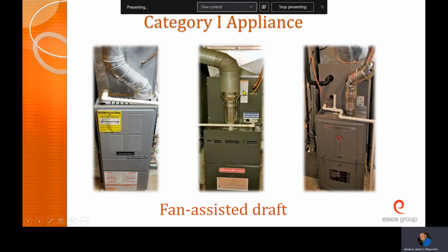But you take that cover off, and inside of there, you've just got an A coil, or maybe an N shape, but you've got a traditional looking air conditioning coil. It's just sitting on top. And so, as I mentioned in the last lesson, one of the things that can cause your furnace to fail is improper airflow, where coils are dirty, fans are dirty, filters are dirty, you're not moving enough air, your duct's undersized, whatever.